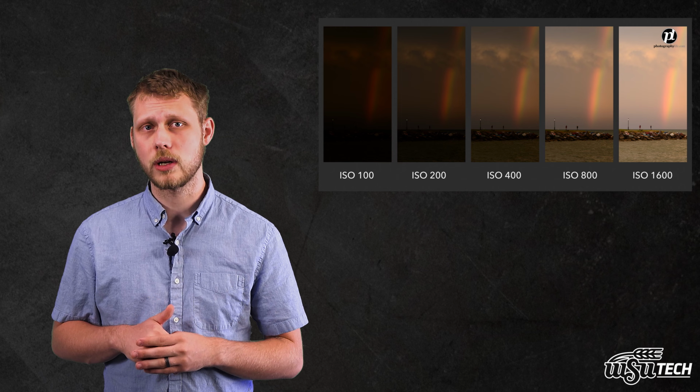Now, let's talk about camera settings. Turn off autofocus. Set your focus manually before takeoff and lock it in. Use manual exposure so your camera doesn't keep adjusting during the flight. Stick with a low ISO to avoid image noise. 100 to 200 is usually ideal.